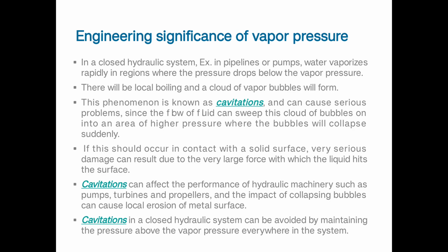Suppose you want to pump a fluid from one place to another through a pipeline, then you have to take care that the pumping pressure should not be below the vapor pressure of the liquid. Otherwise, there is a possibility of formation of local boiling and a cloud of vapor bubbles in it.